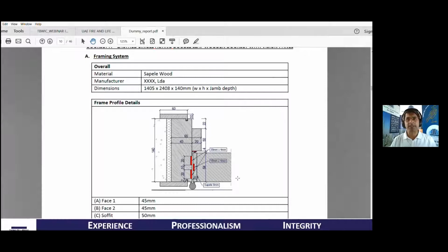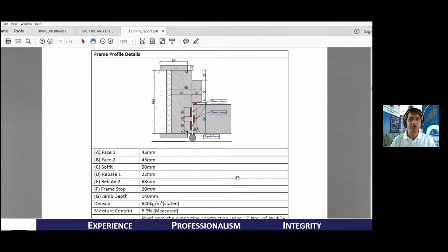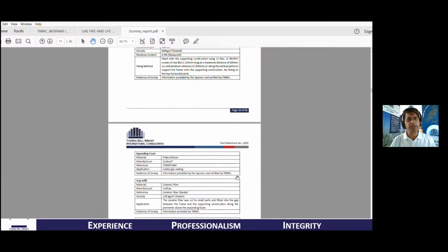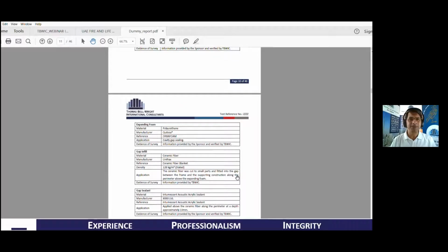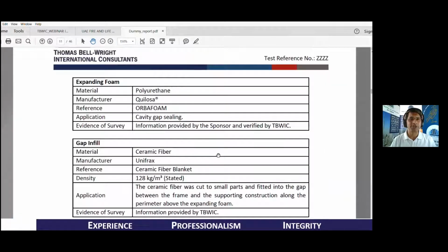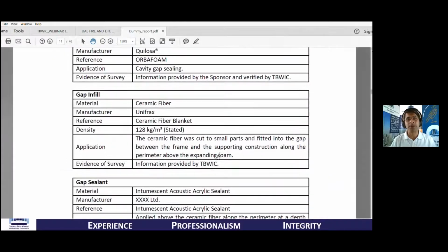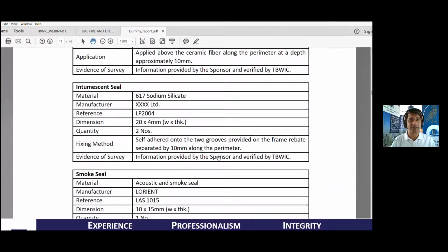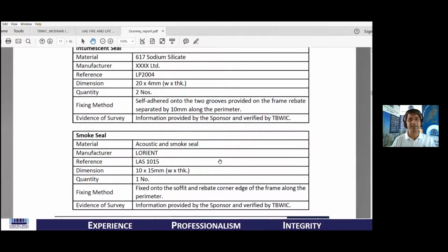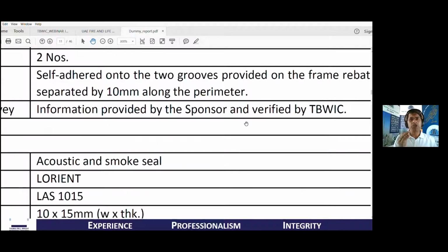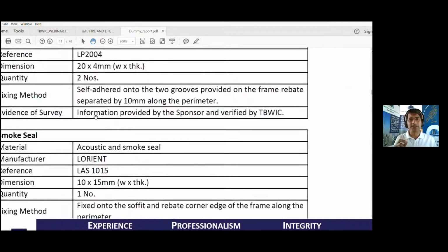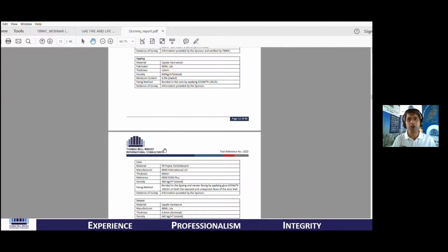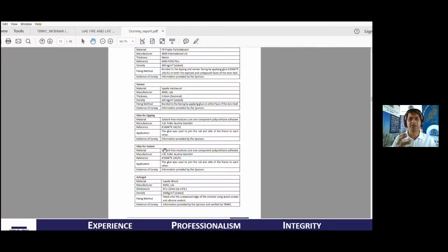The fire resistance test also captures a huge amount of construction and design details. And these details are extremely important from many perspectives. One is, of course, for someone who is using the test report to match and see what is being installed at the construction site, at the supply site, what is it that is there, but also ensuring that a lot of components, materials, where are they coming from, what is their source, what is their dimension, density.